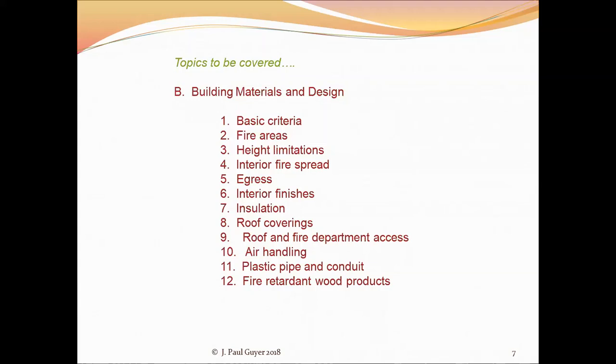And to a lesser degree, the duct system can transmit the fire itself, flames. This occurs typically if you've got some flammable materials in the air distribution system. And so current contemporary design of HVAC systems requires that, first of all, you keep flammable materials out of the air distribution system.